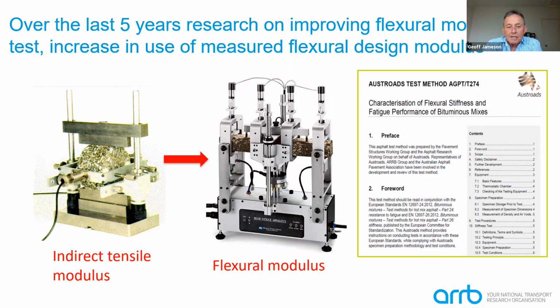In that case, the closest we've got to that situation is our cementitious characterisation, what I described for cemented materials, where you could prepare lab beams if the binder content was sufficient to prepare a lab beam, and measure the lab fatigue characteristics.